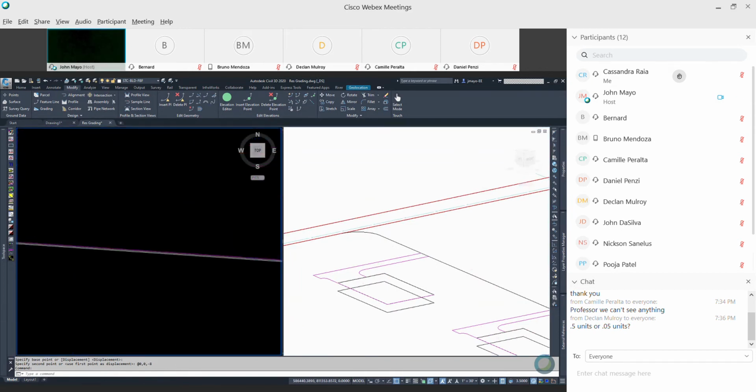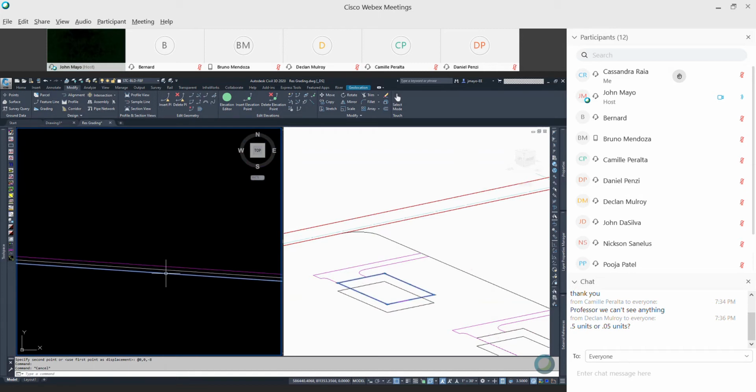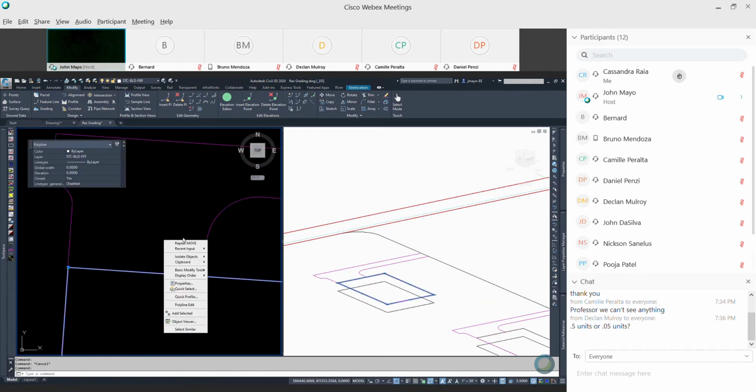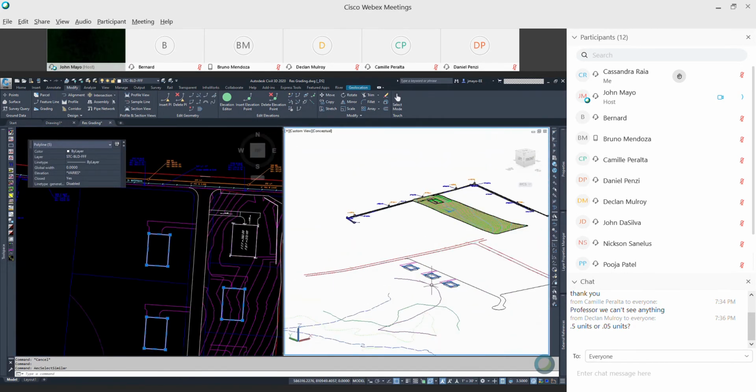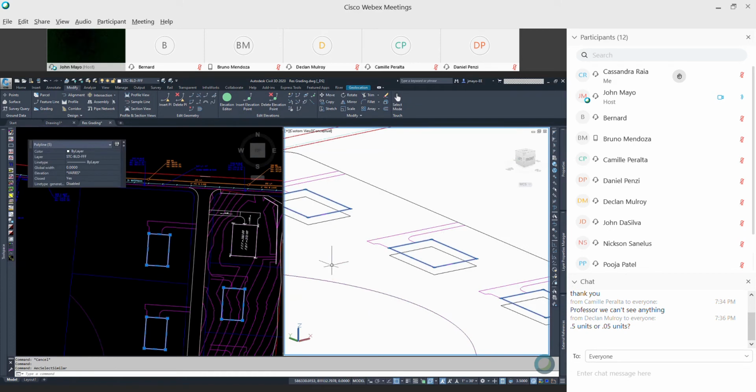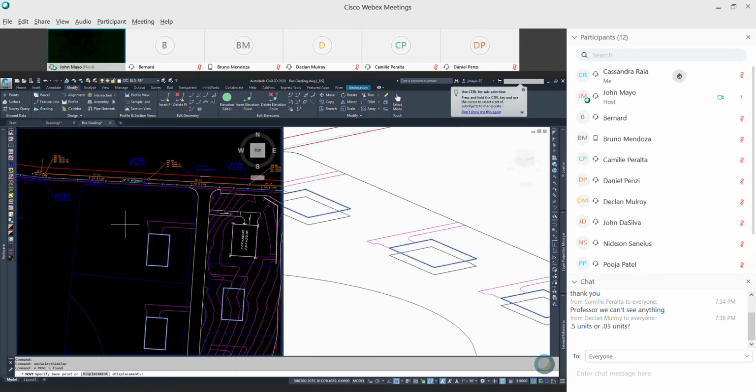Now, if I select all of the first floors, edit, select similar, and move them all up 2 feet using the same relative command. The displacement, I click anywhere on screen, it doesn't matter. I just type @0,0,2.